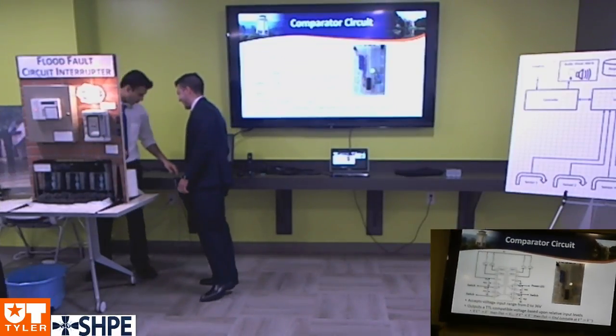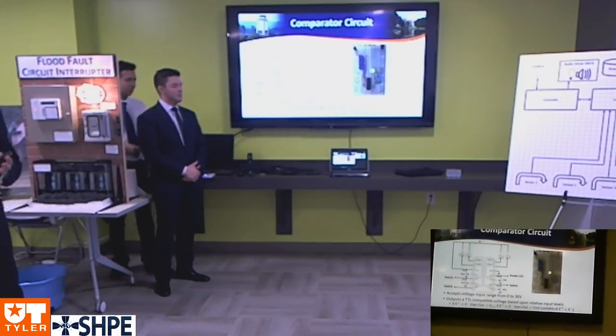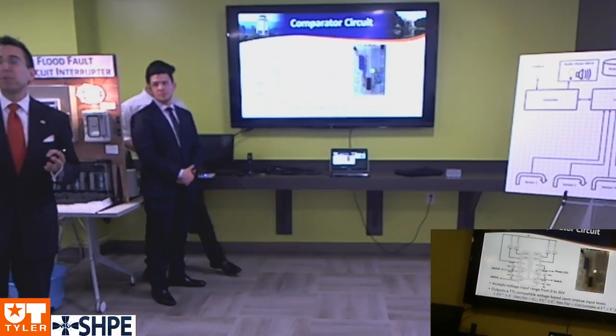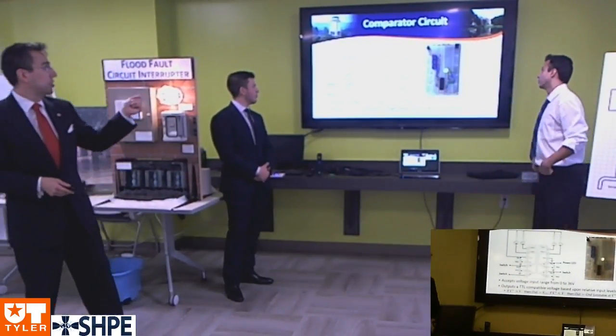So what we've now described is the security panel interface, which has a range of voltages from 0 to 12 volts, but then a standard 5-volt TTL part, which is the EEPROM part. How do we interface between those? And that's where we design in this comparator circuit that you see between here.